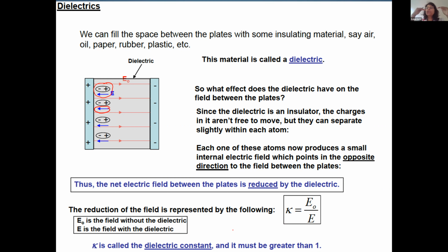That is created because of these dipoles that have positive and negative. So I have an electric field created in between the plates. This blue color E is much smaller than the E naught I have. If you take the ratio of E naught to E, that will again give you the dielectric constant. Earlier I mentioned that this will be epsilon over epsilon naught. That is permittivity information, and this is electric field information. They will give you the same answer.